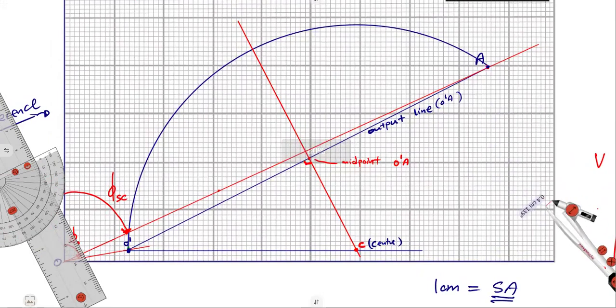So as we can see, we have a semicircle drawn. The needle point at C, you open to this O bar as the radius, then you draw your semicircle to the point A. So it must reach point A. At least that can give you relief in the exam to say, this is exactly what I'm doing, I'm in the right way. But if it does not happen, maybe it is slightly off that point, do not worry. They will mark according to what you have there. All right, so that is about the semicircle.